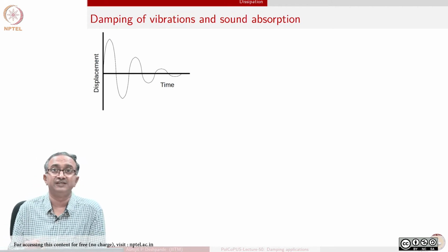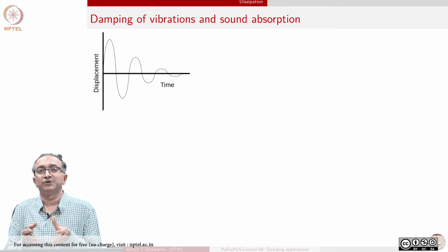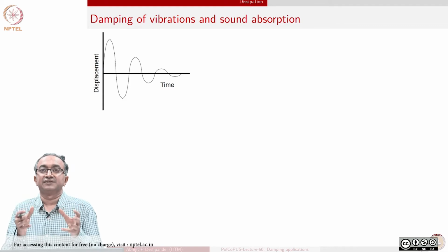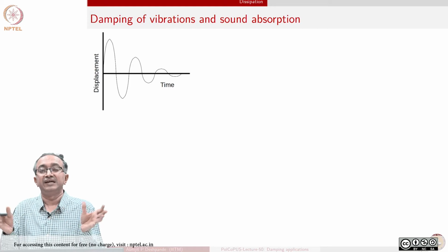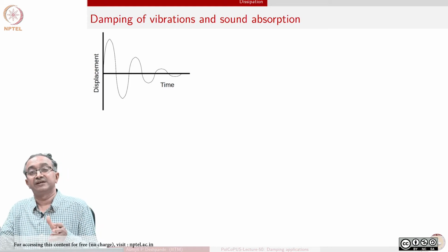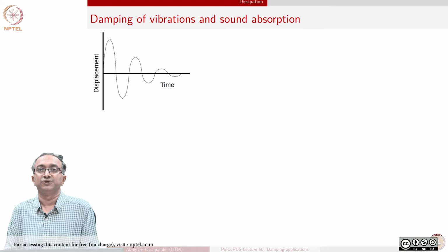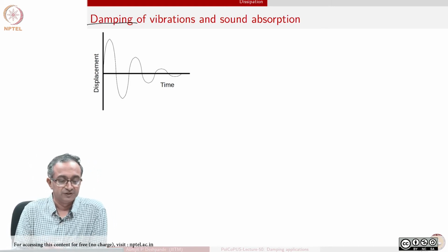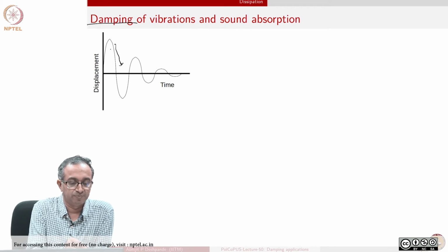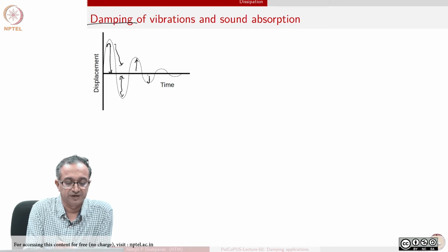So, generally if you look at displacement, a damping material would imply that displacement will die over time. So, whatever vibrations are caused, if I apply some load at some instant of time and the material starts vibrating, then if I leave it, over time the energy of the vibrations will slowly decay to 0, and that is a characteristic of a damping system. So, displacement as a function of time will keep on decreasing. You can see that the amplitude of displacement keeps on going down and eventually of course it will go to 0.